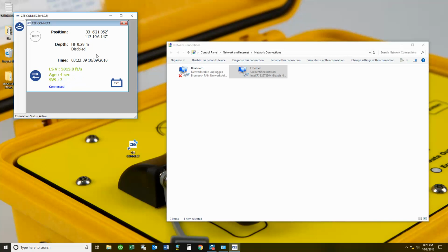If you can see data in CConnect, but you can't see data in your software, assuming your software is set properly, then what's going to be happening is the antivirus or firewall on the computer is activated, and that's preventing the data coming through to the software. The software will be prone to being interfered with by the firewall or antivirus. CConnect is not. So having CConnect gives you a good indication of where the problem lies if you have any issues with your data.